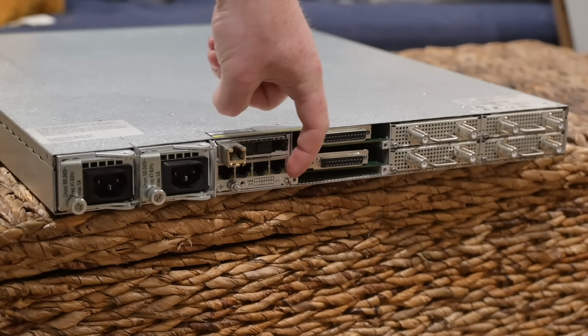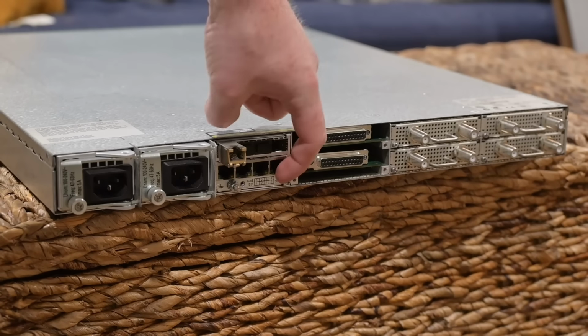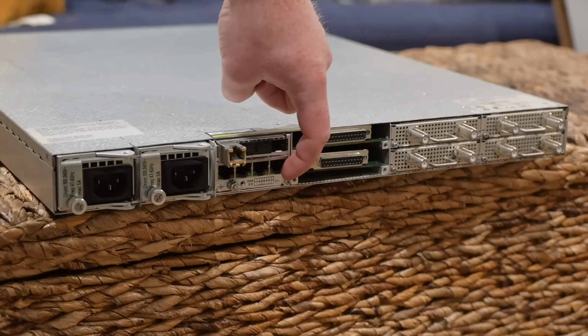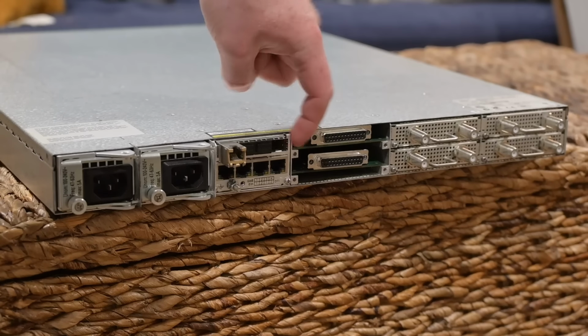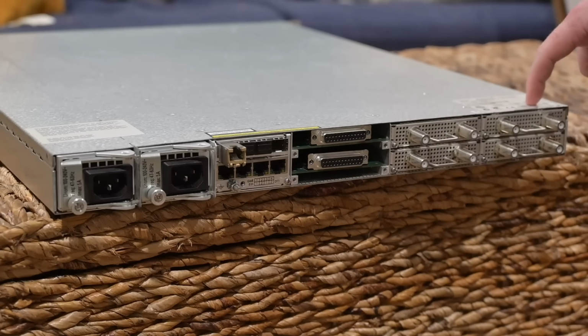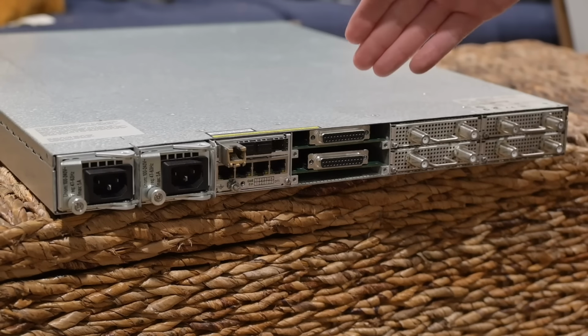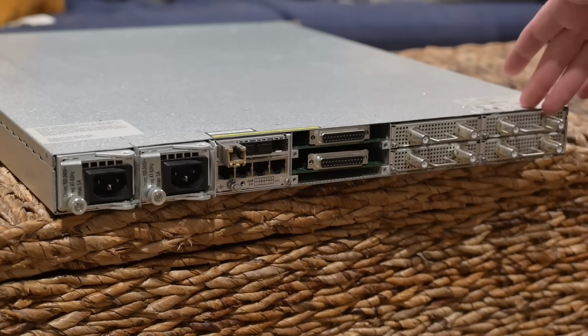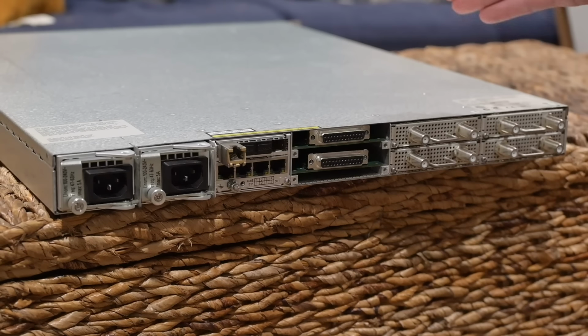Both rows of networking serve a different purpose. The bottom row are RJ45s that support 10/100 Ethernet, and are intended for network management through the web UI, while the top row are gigabit SFP ports that are used for network video stream ingress. Each of these QAM modulators support a total of 8 channels, meaning a fully populated chassis would be able to support 48 channels. Since I have these weird cards though, my unit is currently capped at 32 channels. That will be more than enough for what I'm planning to do with these, so I'm not losing any sleep over it.